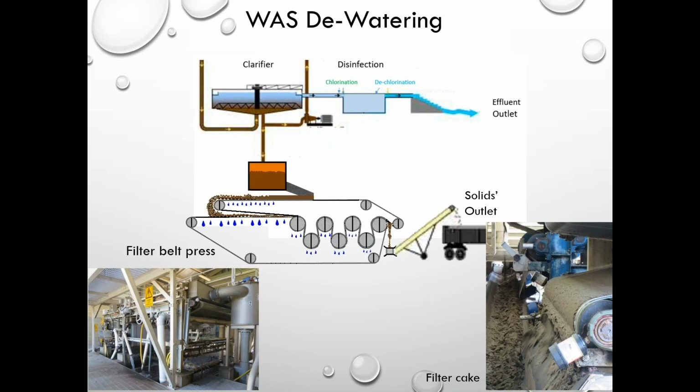For the sludge dewatering, a mechanical filter belt press is used. The activated sludge removed from the clarifier is only 0.5% solid. It is a very wet, turbid mix of the settled flocculants of mostly dead microbes and toilet paper. This removed sludge is called the waste-activated sludge, WAS for short.